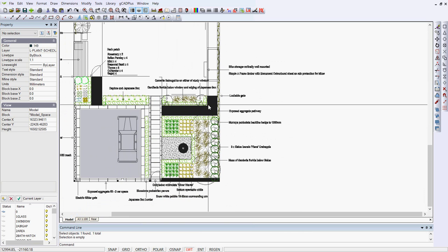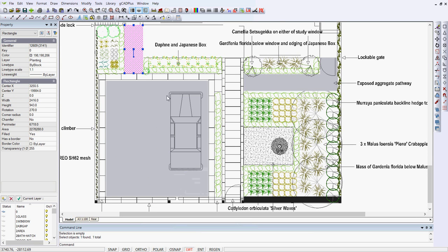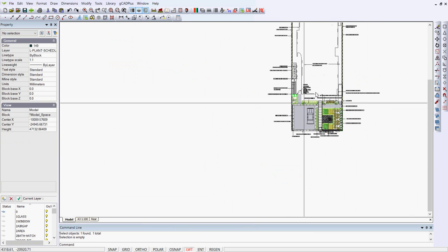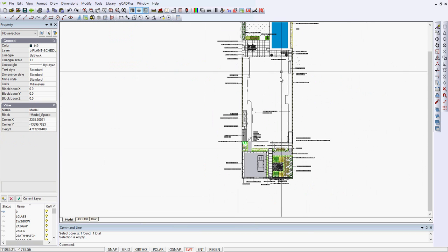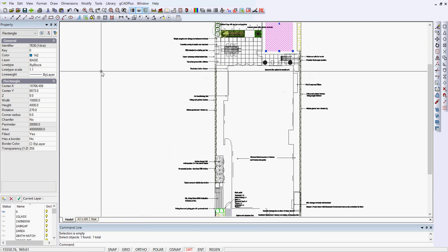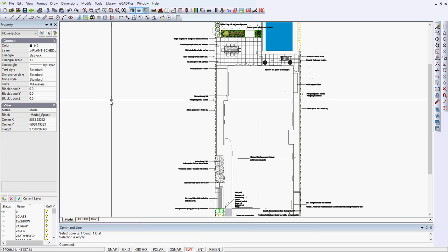It's a lot more efficient to have marked space by just closing a polyline rather than apply hatching. The areas in this design that had the solid hatching, I've now replaced by turning the polyline around each area and saying that it's now a filled area. So that provides us with better definition. If I zoom out a little and pan down, I've done the same with the pool, put it on its own layer called base, and given it a colour so that we have a pool.